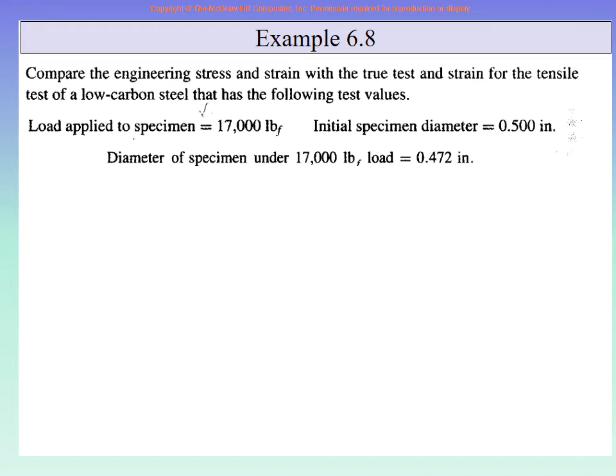You can keep on changing the diameter, you can keep on changing the length. So you can write A naught into what? Volume is what? If I take the area of cross section multiplied by what to get the volume? Right, length. It is a cylindrical piece, so volume is the circular cross sectional area into length. So A naught L naught is the initial volume, at the start of the experiment. At any time later on, it is the current area Ai and the current length Li.